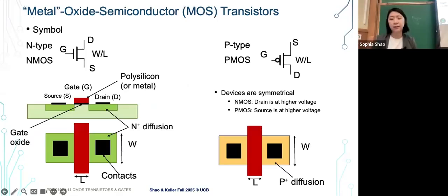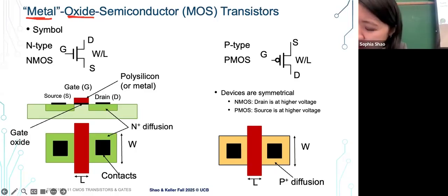If we look inside, when we think about transistors, we always talk about CMOS. We'll talk about the C part later. When we talk about MOS, what does MOS mean? It mentions the different layers in our transistor fabrication process. Fundamentally, we have a mix of a metal, an oxide, and then a semiconductor layer, so that we can create a capacitor that can be charged and discharged to create a conducting channel between the other two terminals. When we talk about a transistor, it's always three terminals. We'll talk about the three terminals later, but one terminal is the gate terminal.